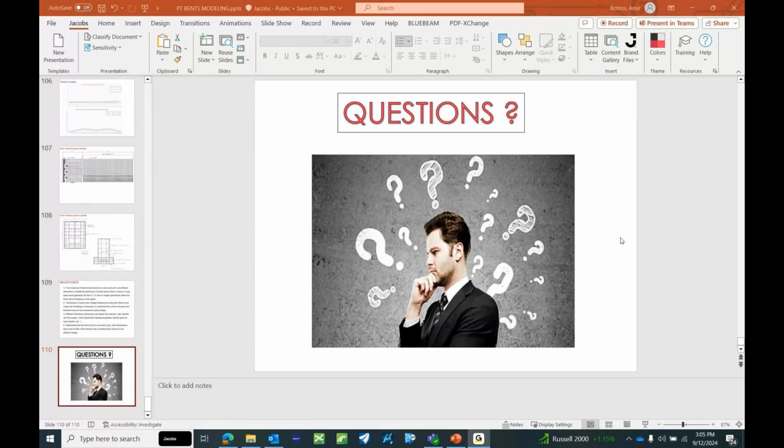And also we basically want to pay more attention whenever we define the durations on each one of those stages. We need to consider defining durations on the stages that are realistic in terms of actual construction, getting input from contractors and the design team on how long each stage would last, because this duration matters whenever the program estimates the effects from creep and shrinkage.